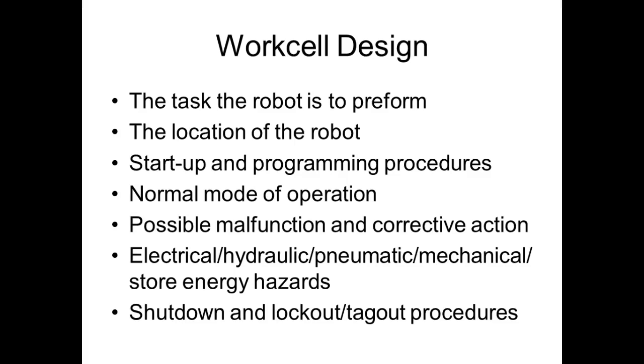Well, you've got to identify who the owner of the lock is, right? Who's the only one that's got the key. So anytime we put a lock on, we put a tag on that lock. And some of the information that's got to be on the tag is who the lock belongs to. That makes sense. We can tag without locking, but we can't lock without tagging.